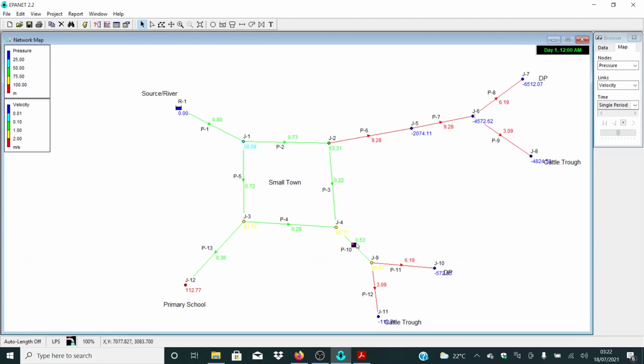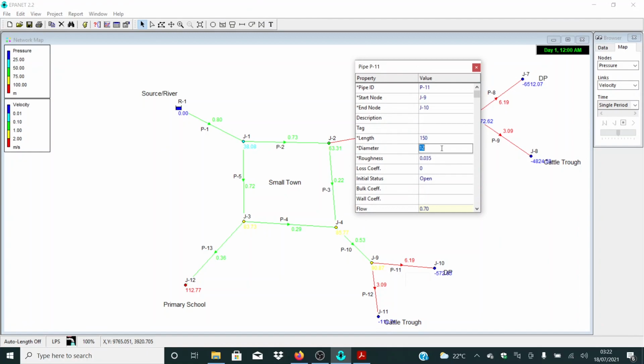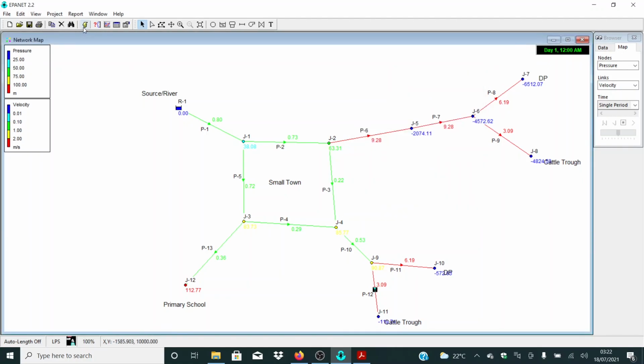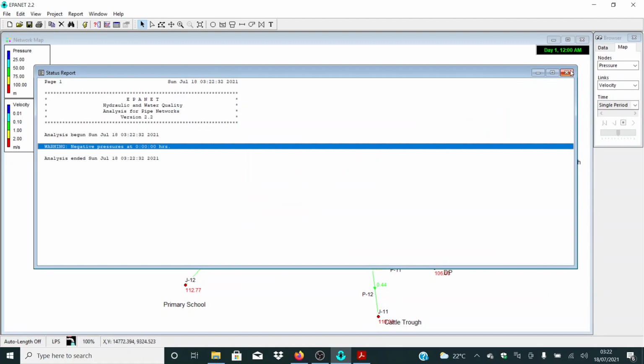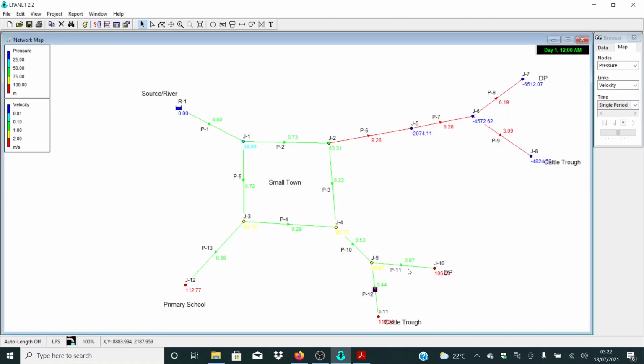So you can see now we have 0.5, which is good. And again, let me use the same value in this area. So in this area, let me use 32. Remember, this is internal diameter. Make sure that you are using internal diameter, not outside diameter. Let me run again. You can see now at least we are having this kind of values here.